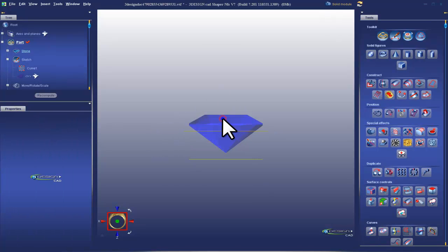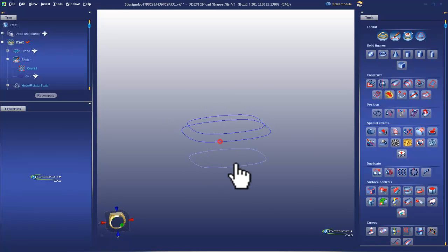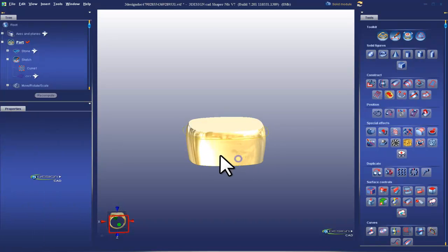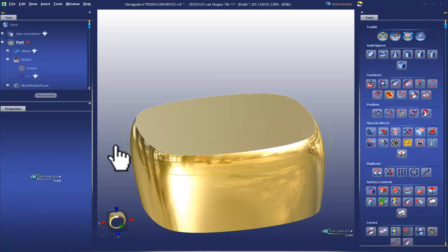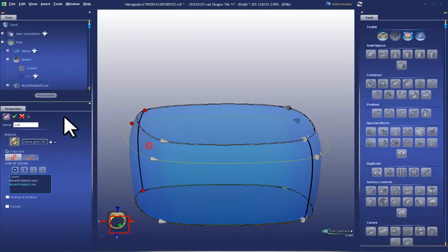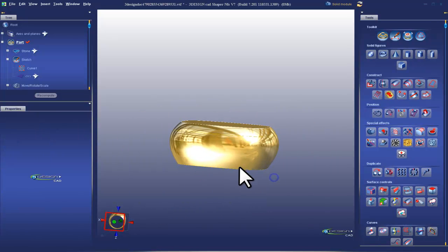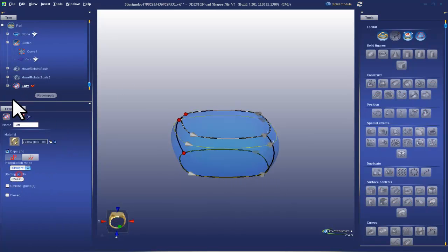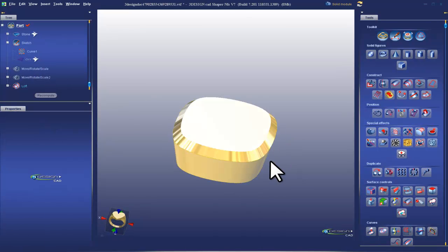All right, so now I have 3 curves, and they're all copies of each other, and I could choose 1, 2, 3. Loft those. Okay, so this is on loose interpolation, you see? Now we'll change the interpolation to normal. And we get this. And then finally, straight. And we would get something like that.